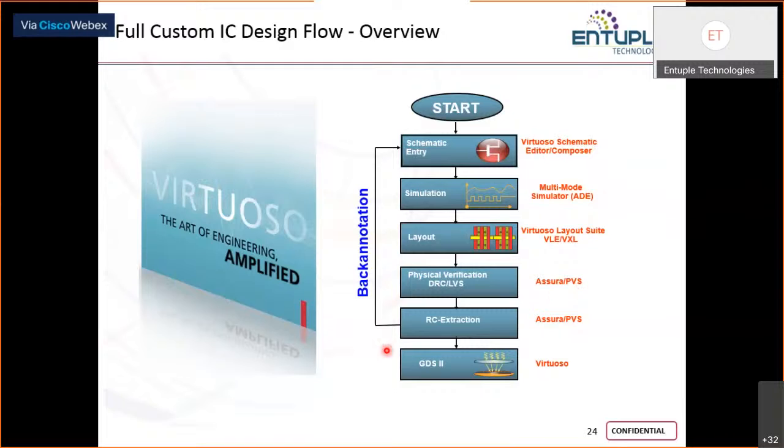And then we come to RC extraction. Extract the parasitics after you complete your layout. Extract the parasitics and check their impact on your circuit. What is the impact of those parasitics on the timing aspects of the design and the power aspects of the design.